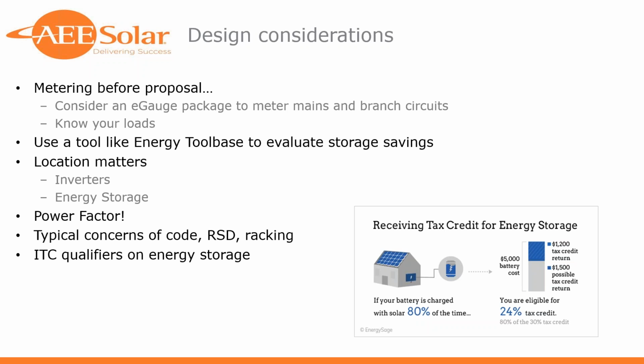So we're getting to that point where we're going to have to take that milestone into account, because, excuse me, I said 2018 and I meant 2019. January 1st, 2019, in a lot of areas, there's an addendum. There's a TIA that's being applied to NEC 2017, which will require module level rapid shutdown.